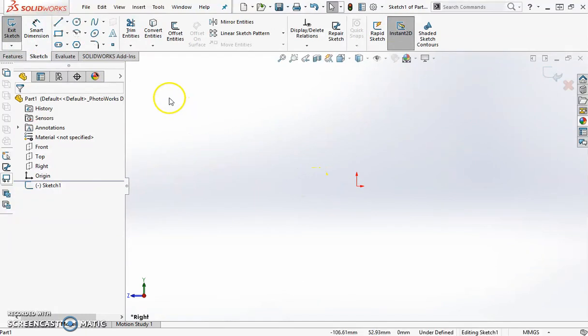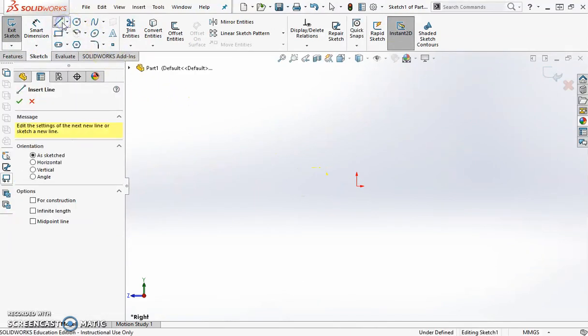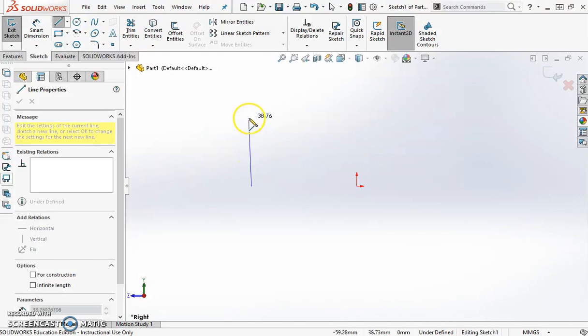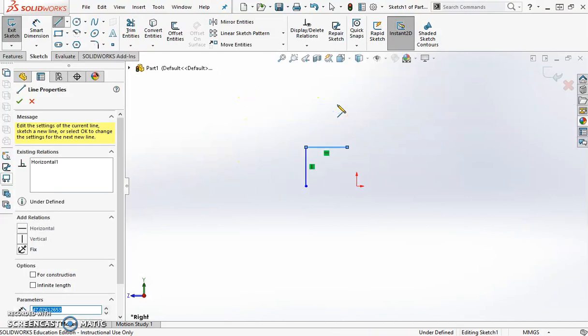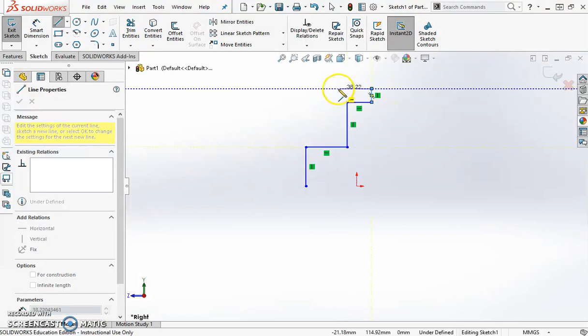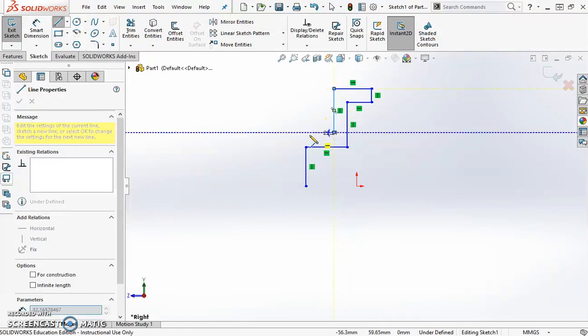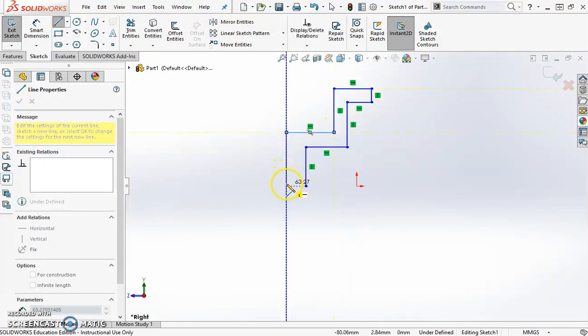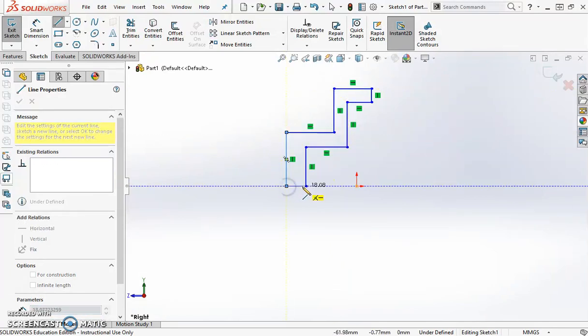So from here, I'm just going to get the line tool, and I'm going to kind of sketch out that staircase looking shape. Make sure you're not on the origin, because if you look in your picture, nothing is attached to the origin, but you might want to project over to the side. These are all vertical and horizontal lines. Just draw this zigzag shape up and then follow your way back, and at the very end, you're going to connect back to where you started.